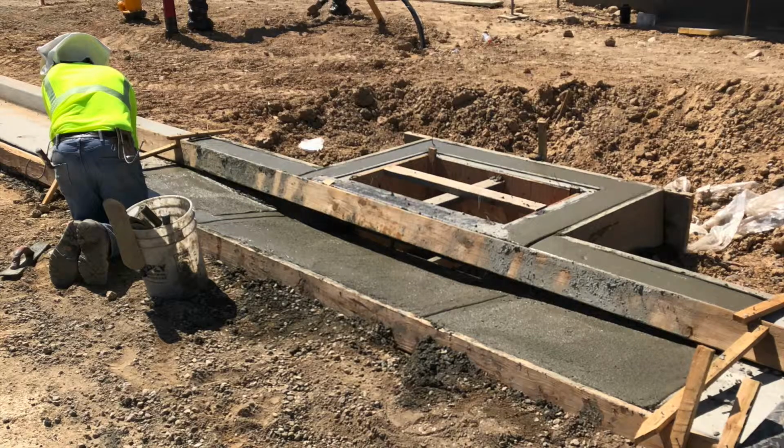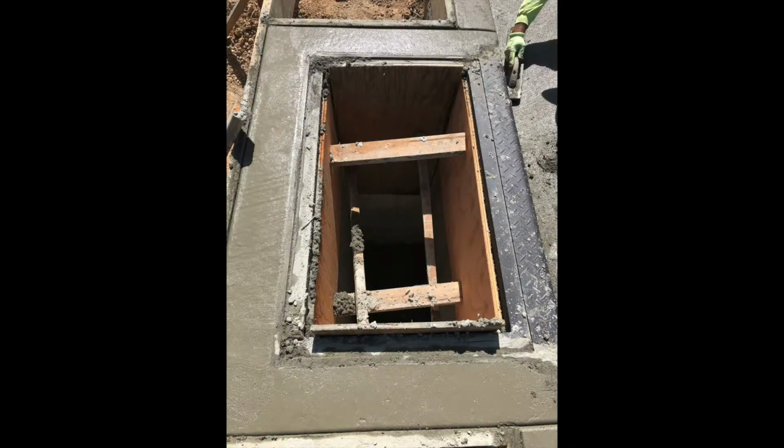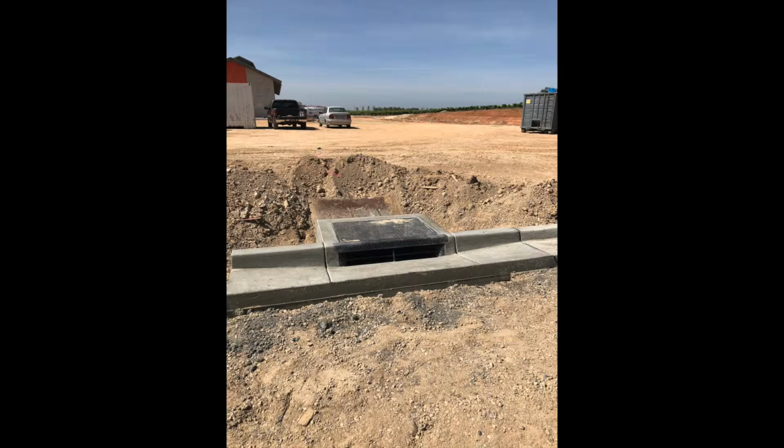All right, this is something that you'd be more likely to see on a job site. This particular laborer is finishing a concrete DI, or drain inlet, that they just poured to match up to existing curb, as you can see. In this next picture, you can see they had to place what's called shoring inside, and that keeps the concrete contained, so it doesn't fall in on itself, essentially, and it can maintain its shape. And this is what the finished product looks like. This is a completed DI, or drain inlet, out here in Madera, California, in this particular instance.